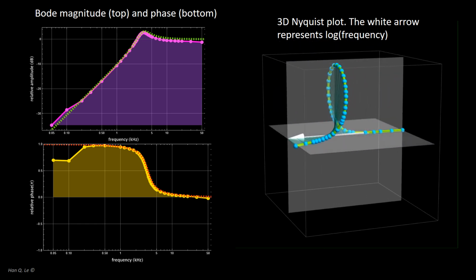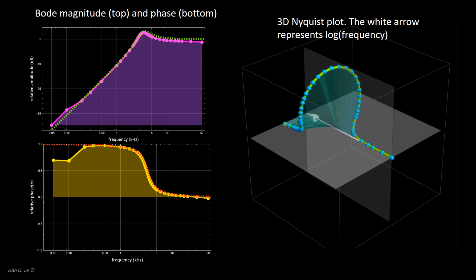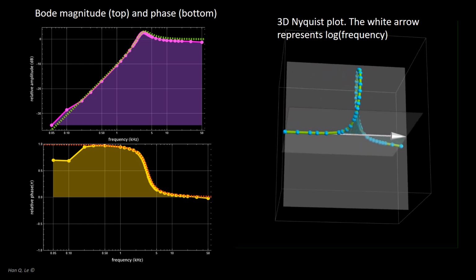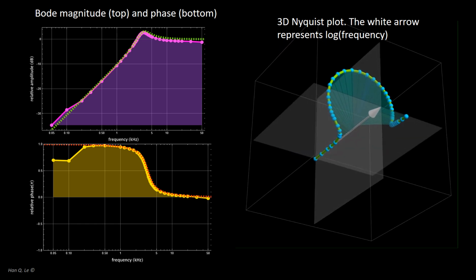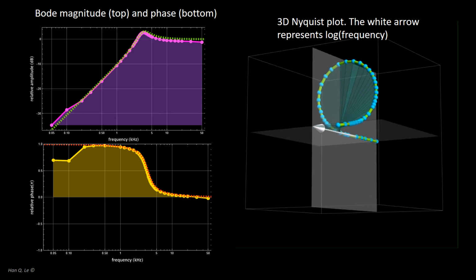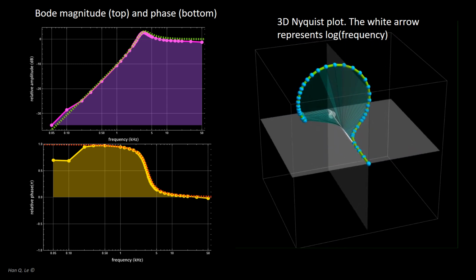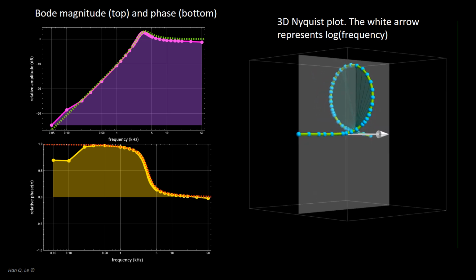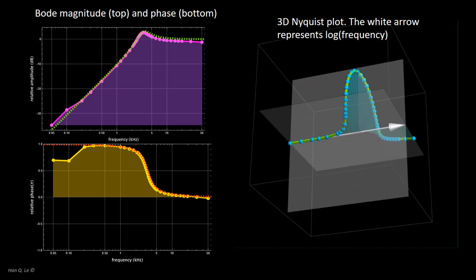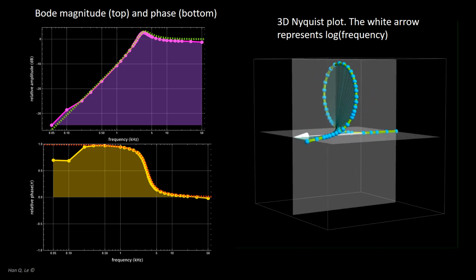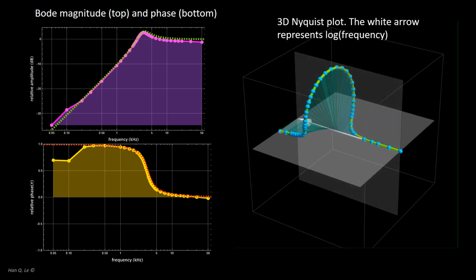For the Bode magnitude and phase plots, the dots and the solid connecting lines are experimental data, the dashed curves are the model calculation. The model does not include the realistic gain bandwidth of the LM741 op-amp, hence there is some discrepancy at the high frequency end. Also, the calculation uses nominal values of the resistors and capacitors. No adjustment was made to fit the resonance frequency.